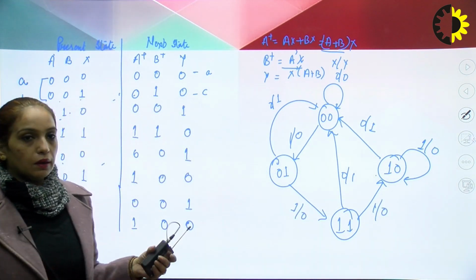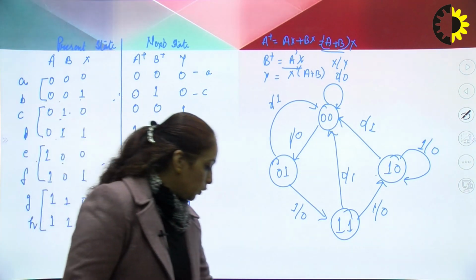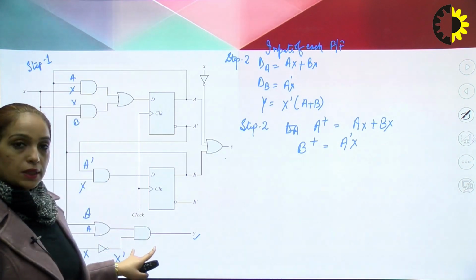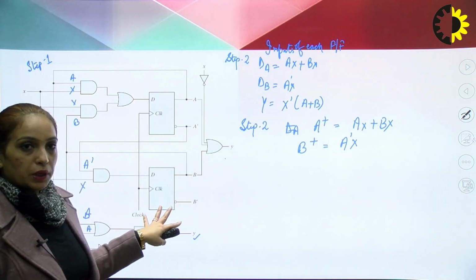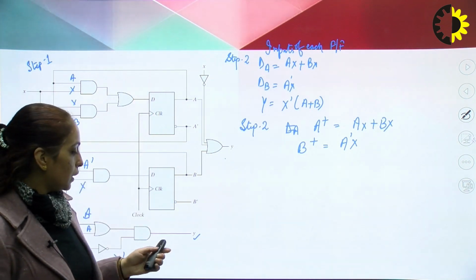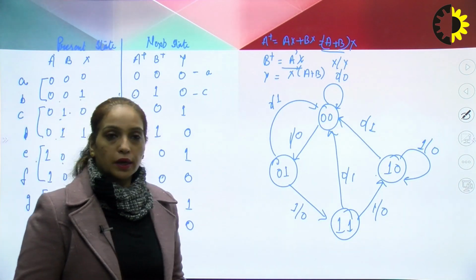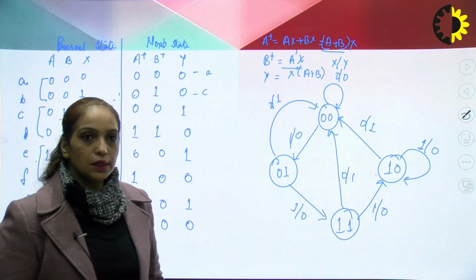So this way we can analyze this circuit where your inputs are applied via some combinational network and the output is collected via some combinational decoder, and we have this memory part with n number of states, right? So this way we have to find out what kind of circuit it is, whether it is Mealy or Moore. Accordingly we have to draw the state diagram.